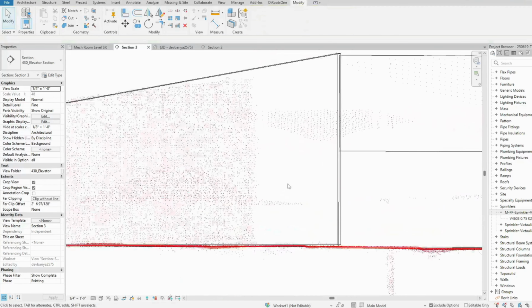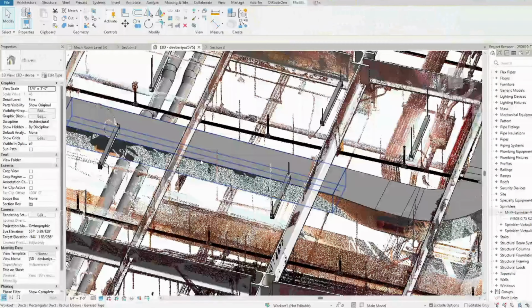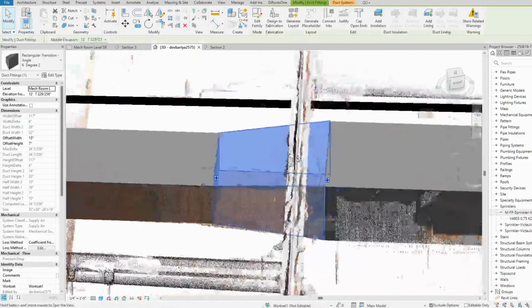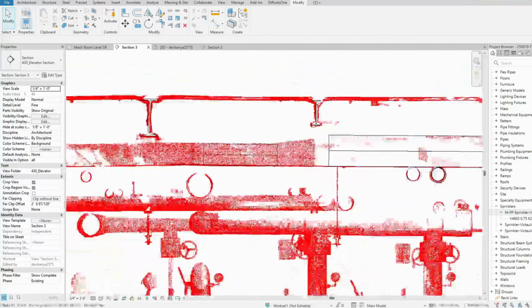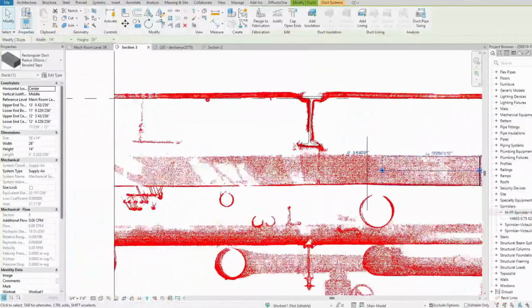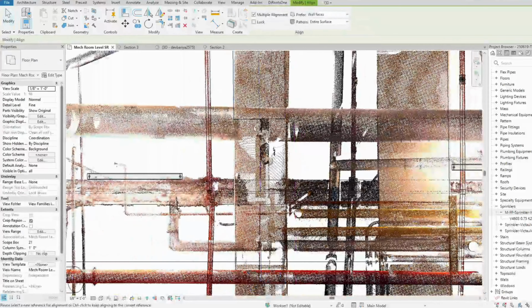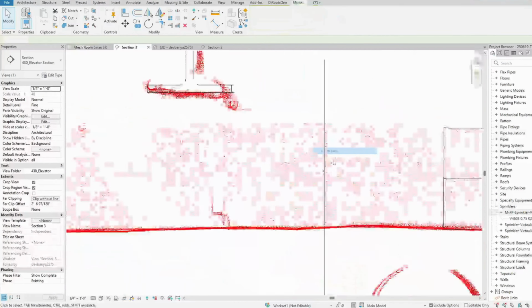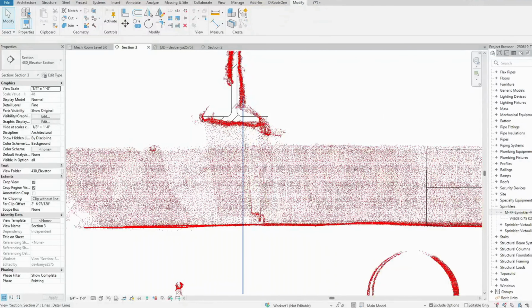There are also settings for material and insulation. These are important if you're doing detailed work like quantity takeoffs or cost estimation, because Revit can calculate how much duct material you're using and whether it's insulated or not. This is where Revit goes beyond just drawing lines on a screen. It's not just a visual tool, it's a smart modeling software. Every duct, every fitting, and every air terminal contains real data. This data helps you do things like coordinate with other systems, detect clashes with pipes or beams, and even estimate how much your ductwork will cost. All of this makes your BIM model much more powerful and accurate for real-world construction projects.